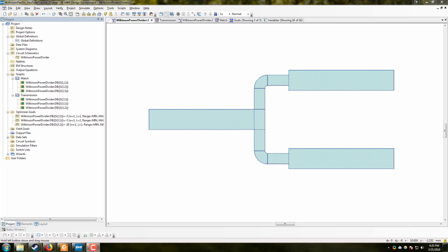When we get to RF, when we get to microwave frequencies, we no longer make these assumptions. Now we know that the wavelength is either very close to the physical size of the component or it's less than the physical size of the component. So the lumped element model no longer applies.